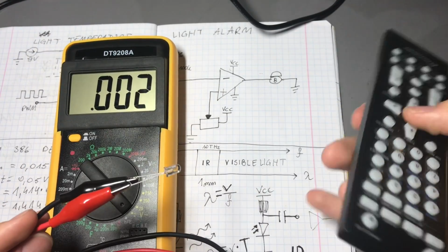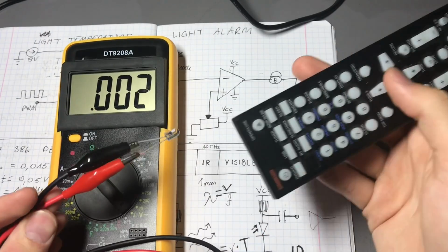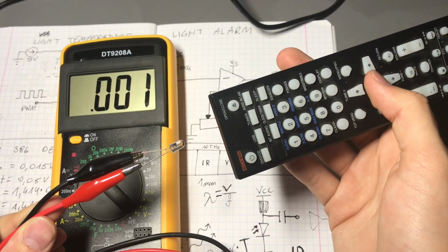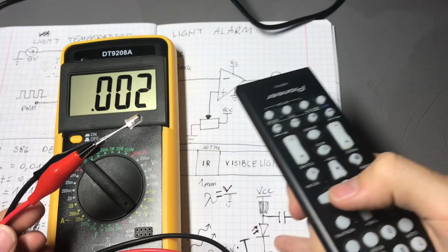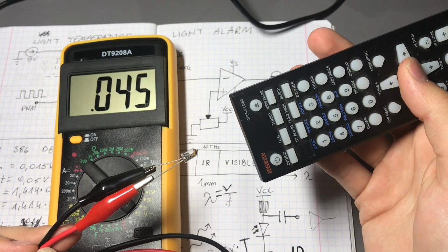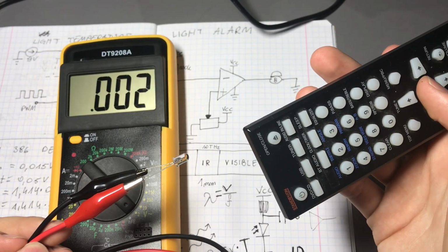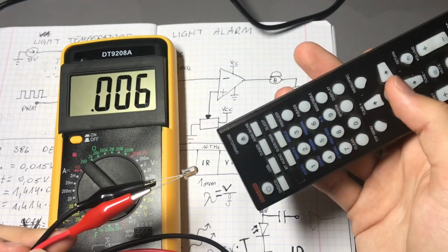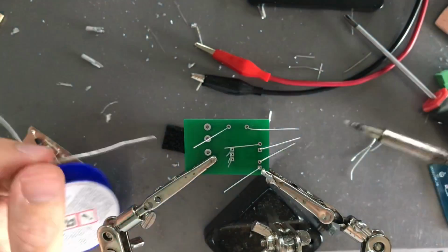Of course, the photodiode here works a bit more like a phototransistor, but it can generate its own signal too if you connect it straight to the amplifier. It creates a higher amplitude signal here, so it's easier to amplify. But anyway, let's now show you some practical examples of how to use it, and for example some waveforms and some other interesting stuff. So let's go on and do it.